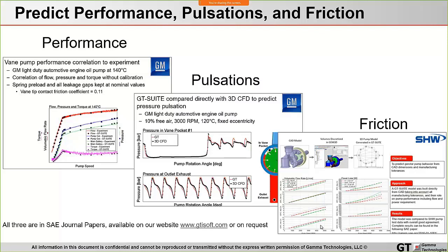Another bucket is the ability to solve for wave dynamics and pressure pulsations from the machine. And here's an example right in the middle, again looking at a GM oil pump, and this time looking at the pulsations, and you can see the comparison to 3D CFD, not only for pressures inside a given chamber, but also delivery pressure pulsations.